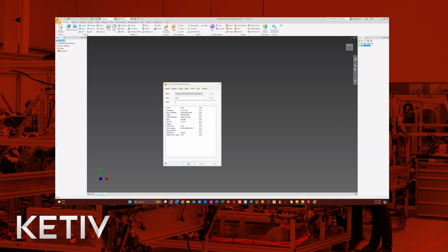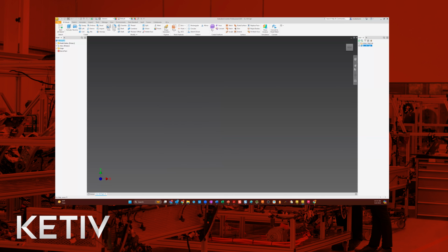So we want to create a finish property. Typically, you would create the finish property in Vault, your user-defined property, but if you wanted to participate with Vault Data Standard, it also needs to be here initially in one part so that you can import and map the property. Let's go ahead and show that here. Do finish, and we're going to give this a value of black oxide. And we're going to add that. Apply it, close, and save.